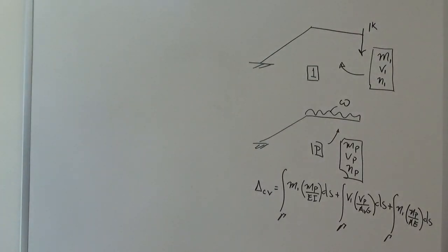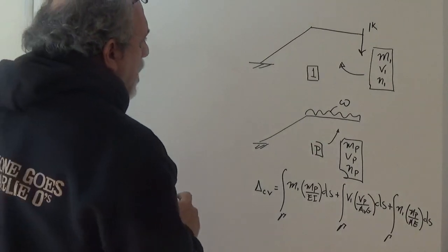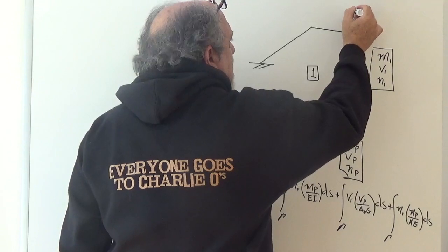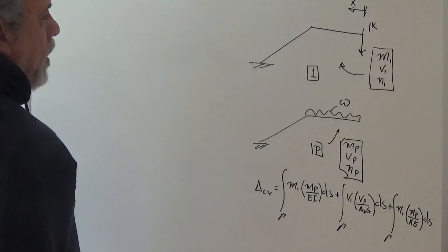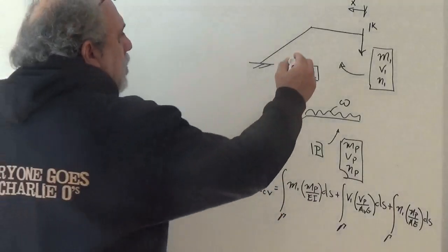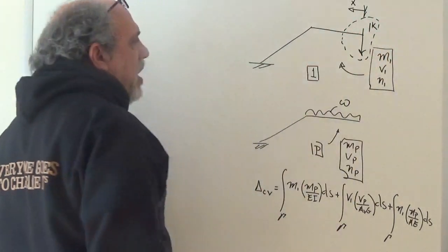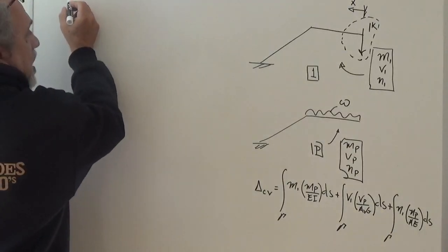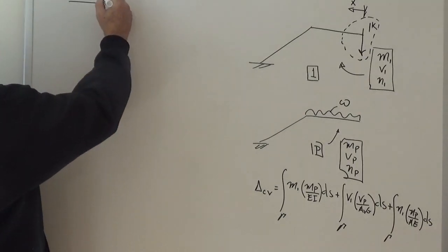So let's start with our right side. Let's start with our unit diagram, right? So I'm going to state that the coordinate x starts from that end and runs to the left. With that coordinate, I'm going to take this bubble as a free body diagram. And from that bubble, I start here on the extreme left, so I have that, I see the one kip.